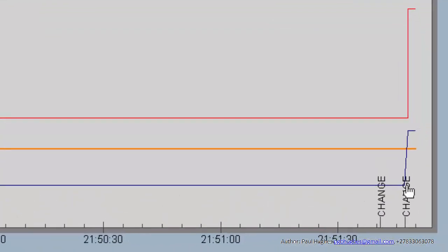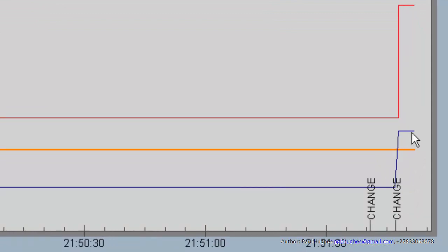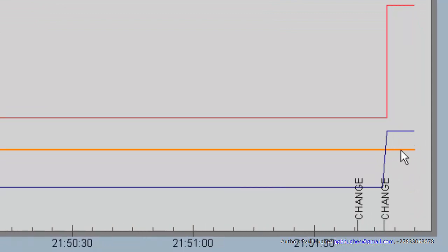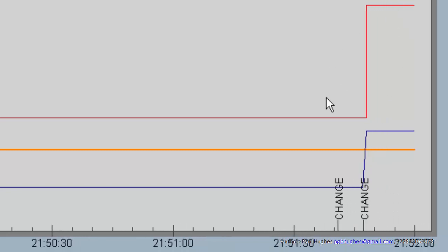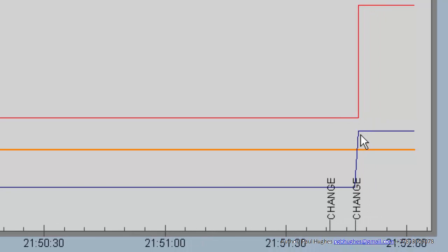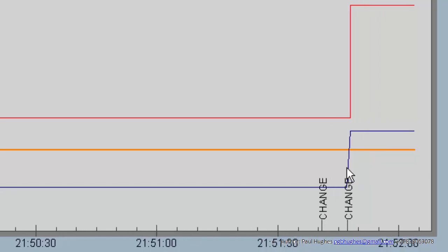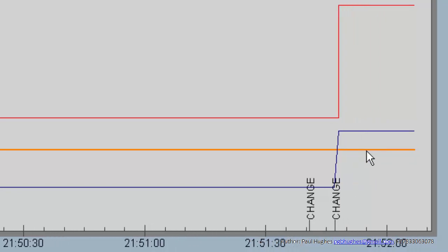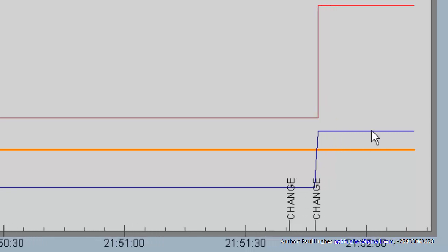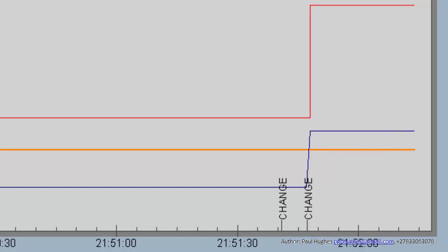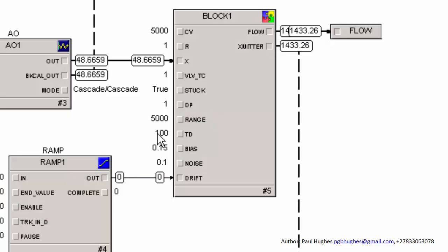And as we can see, once again, proportional action kicks in. Because the PV hasn't changed, only the error changed for that one scan cycle. You have a kick in the output. It's your proportional action on error only. PV is not changing now. Integral basically has no effect, so you've got no effect on the output. If you go back and look, you'll see the output is slowly changing, but it has no idea that it's stuck.